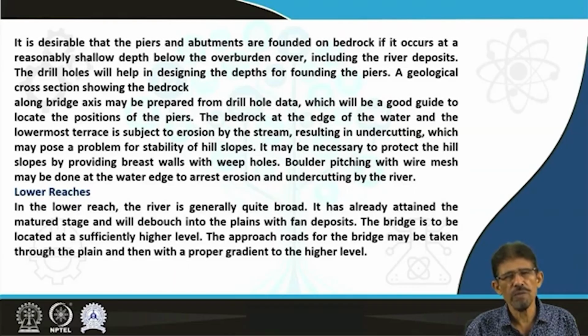In lower reach, we face similar situations and require a long bridge, and this long bridge requires a number of piers. Some may be located in the water body also, which requires special precautions on one hand. On the other hand, the typical behavior of silty clay and clay requires careful experimental work for determination of liquid limit, plastic limit, plasticity index, bearing capacity, cohesive strength, angle of internal friction, and others.